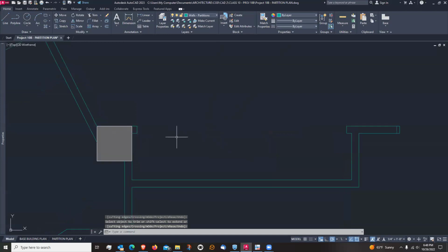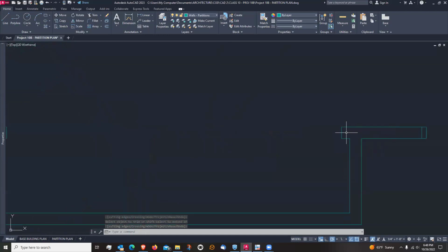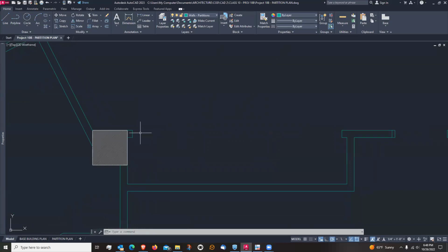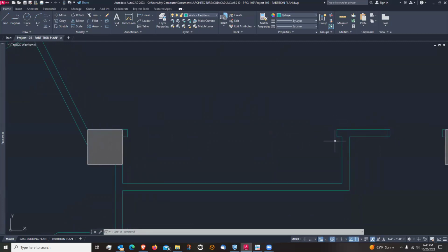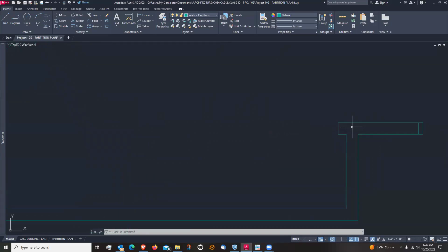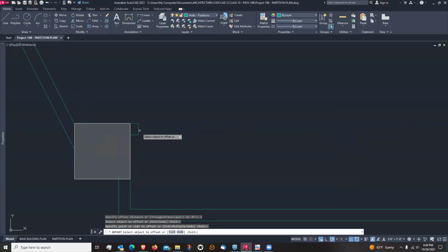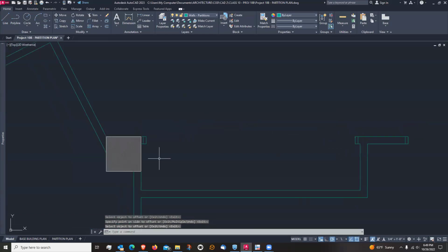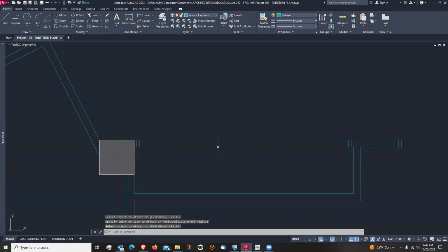So sometimes closet doors have a door frame around them, and sometimes they don't. Sometimes it's just drywall that's going around. Whenever you're designing and you just want the drywall going around, then you would leave it just like this. But if you're going to put a casing, a wood casing or a frame around, then you want to show that. So they're showing it in the handout, so I'm going to show it here. Just 2 inches. There we go. So now we've got 4 doors.